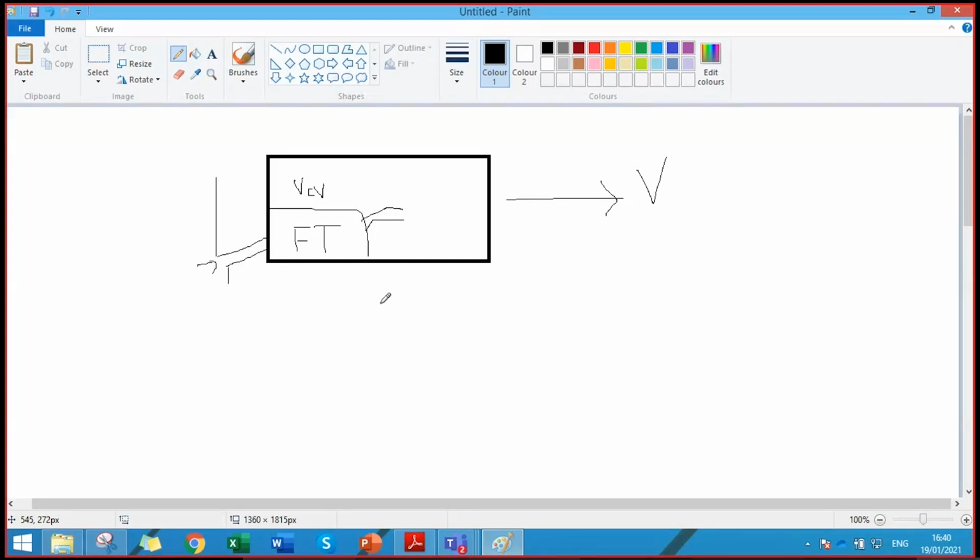For this, we need to have the observer perspective. From an observer that is sitting in the vehicle, let's say there is an observer here, observer A. From his perspective, the control volume is fixed, right? Stationary. From another observer, let's say observer B, who is standing on the road, from his perspective the vehicle is moving and the control volume is also moving, right?